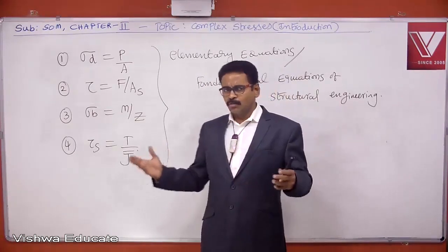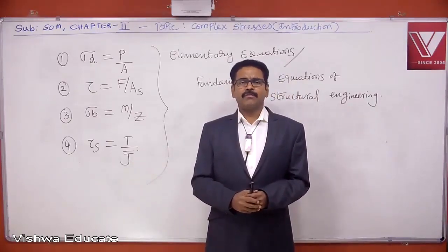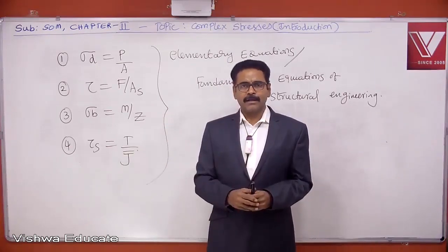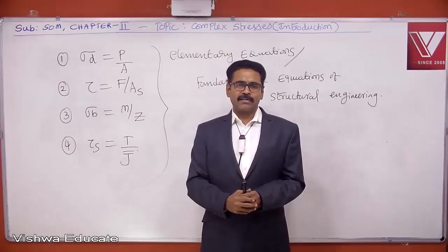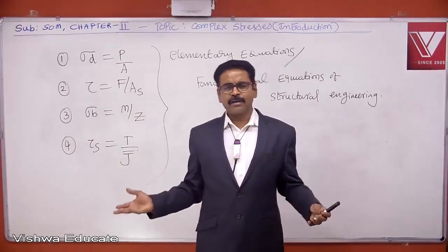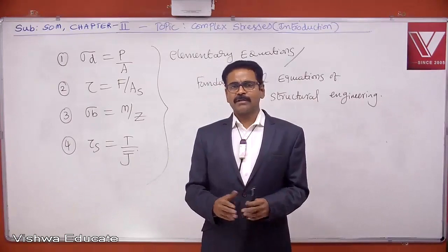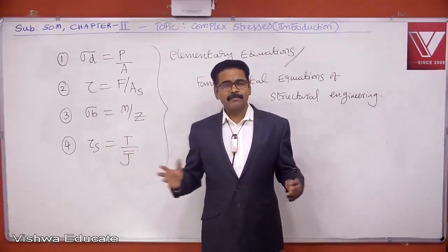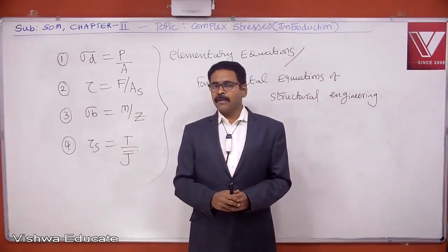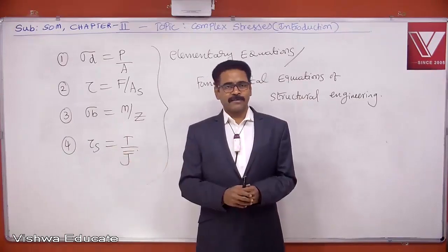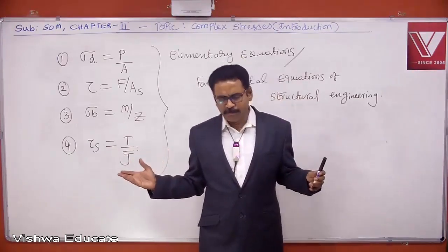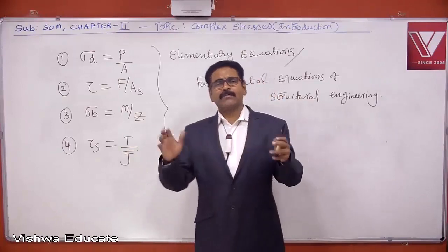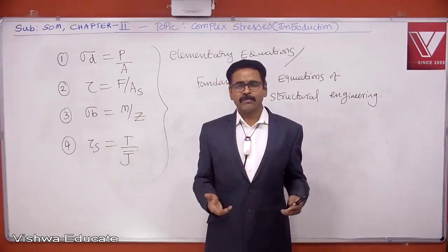Any plane means whichever plane carries highest stress, about that plane failure occurs. That failure plane or critical plane need not be always cross-sectional plane and surface plane. Sometimes, failure plane will match with cross-sectional plane. Sometimes failure plane or critical plane matches with surface plane. But not always. Failure plane may orient about any plane. Critical plane may orient by any angle, we don't know. It is function of type of material, combination of load, amount of load, etc.